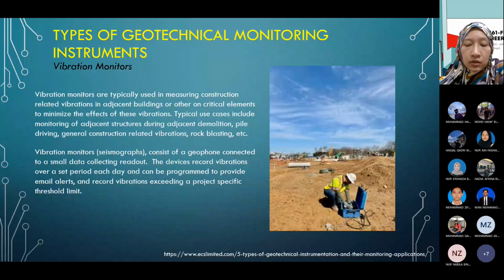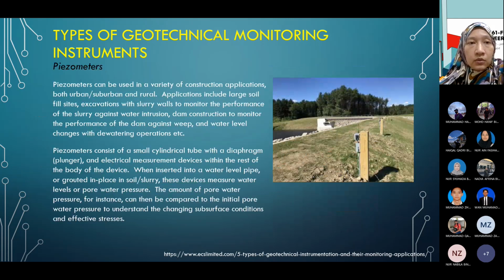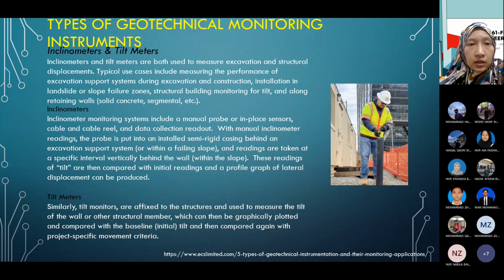So the vibration monitors, if you search online, there's a lot of equipment right now on the slope stability that can be observed using a radar. The radar gives you information on capturing slope, potential slope failure. So it gives you the information and the chances or the stability of the slope by using the latest advanced technology in instrumentation. So something that I showed here using manually, or something that can be integrated with digital measurements.